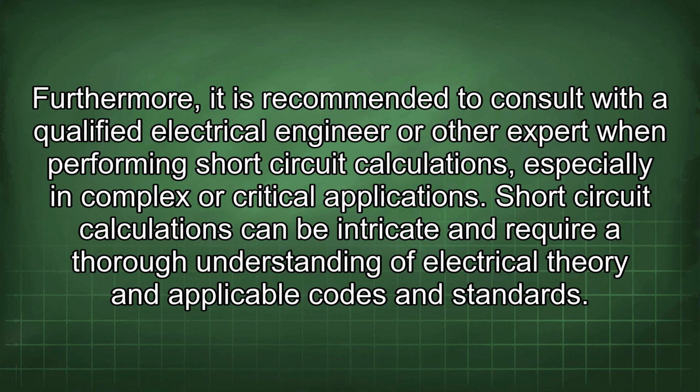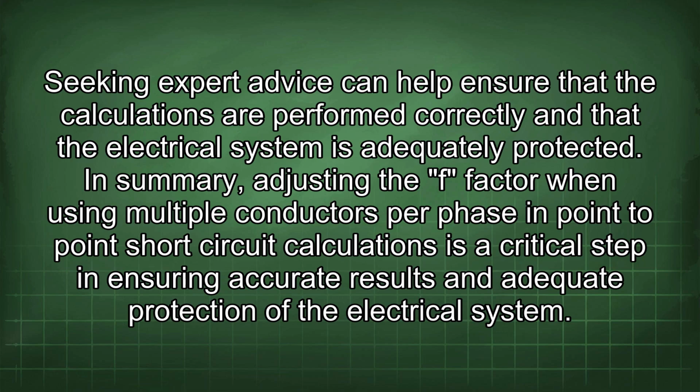Short circuit calculations can be intricate and require a thorough understanding of electrical theory and applicable codes and standards. Seeking expert advice can help ensure that the calculations are performed correctly and that the electrical system is adequately protected. In summary, adjusting the F factor when using multiple conductors per phase in point-to-point short circuit calculations is a critical step in ensuring accurate results and adequate protection of the electrical system.